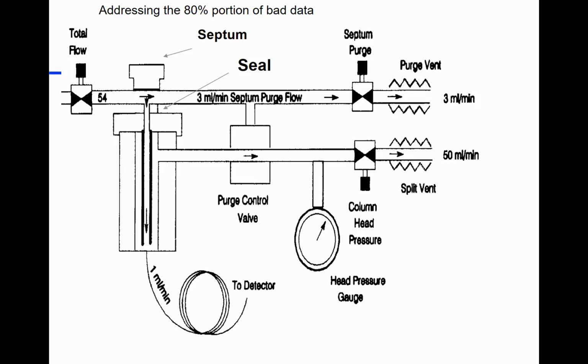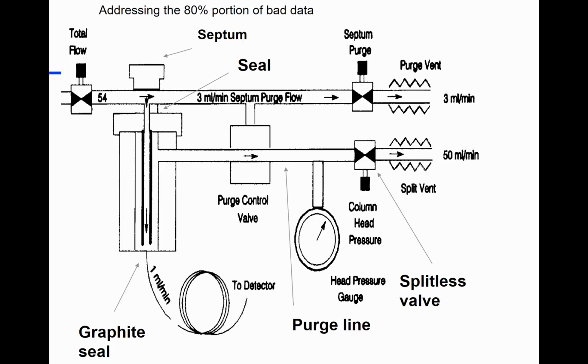You need to make a seal between this steel body and this glass tube. Again, a nice O-ring here. We've got to make a connection between this long little column and all the gas that's flowing down here. Another place for leakages to occur. Sometimes this valve here that controls the flow through the injection port ends up being messed up. And so there's, again, lots of opportunities.